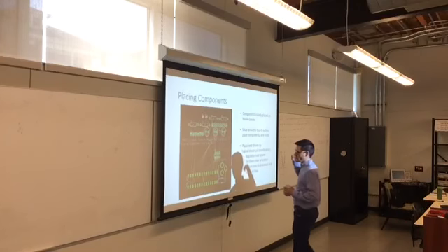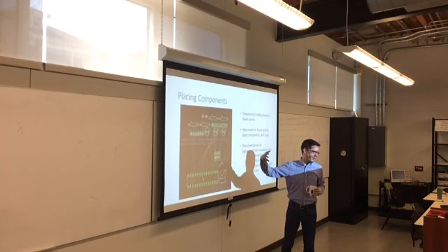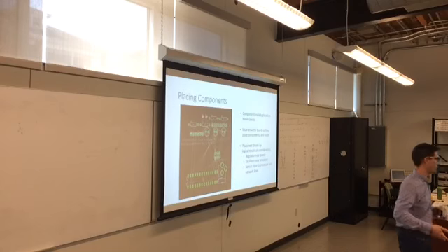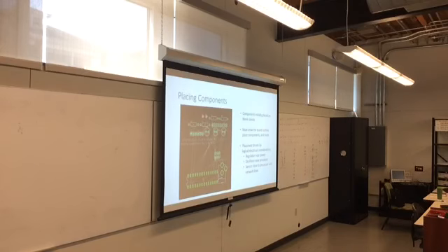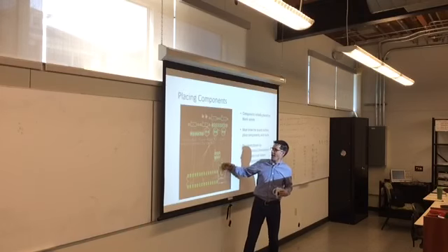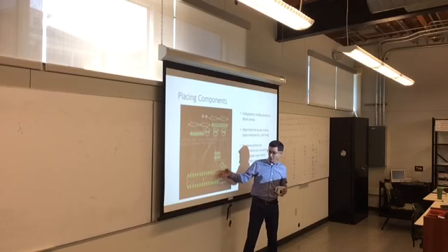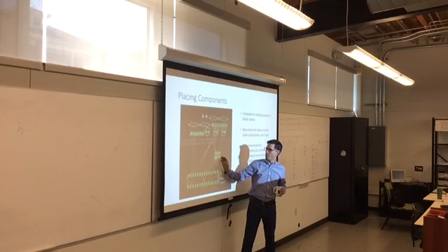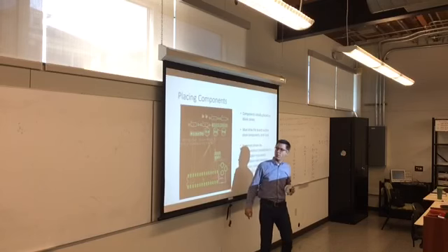So the layout tool has no notion of where these parts belong because your schematic gives no indication of where they physically belong. It stuns me that no one has solved this problem because when you do FPGAs, there are placement algorithms. But whatever. The fact that it's just going to randomly drop my processor and my power jack and then this in the middle here, the challenge with this is that you have to now, it's a giant game of blocks. You have to lay out these parts in an area such that they're close to one another, but that then when you route them, all the lines don't overlap.